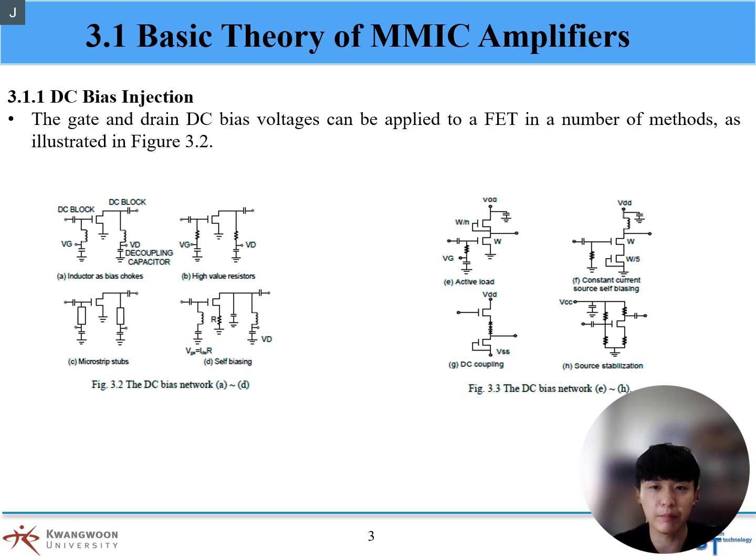In Method D, the self biasing technique is used, enabling the FET to be biased from a single power supply rail. The advantages associated with the single power supply are significant, particularly for battery operation, but there is a general penalty caused by the slight increase in DC power consumption. One drawback of the technique is that it removes a useful post-fabrication tuning mechanism from the amplifier because the bias is fixed.